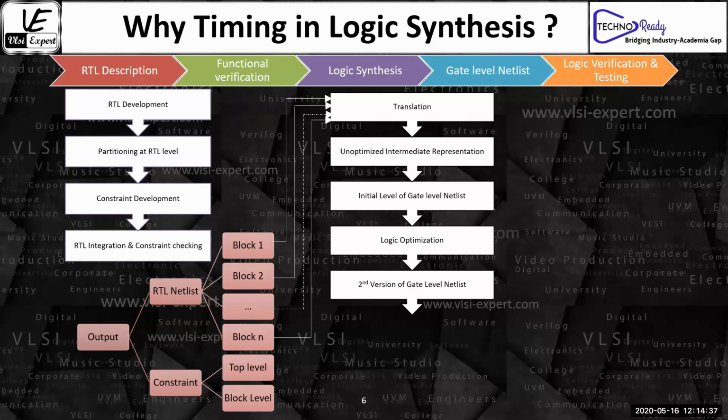So if your pre-layout design, or you can say the post-synthesis design, itself has a problem in setup and hold, and a couple of timing problems are there, where we are considering most of the factors as ideal factors, if you are having a problem at that particular moment, then obviously you cannot fix it post layout, or you can say at placement time, or from the physical design point of view. So that's a part of logical synthesis, and that's the importance of the timing at this particular moment.